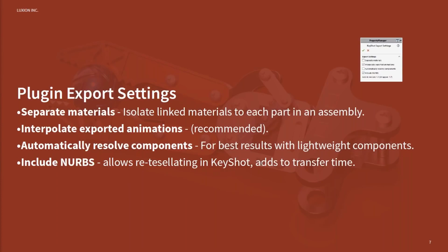And actually, for now, it is not remembered when you close and reopen SolidWorks. So just make sure to check those settings each time you're opening up a new session of SolidWorks, just to make sure that you have those enabled correctly. So if you do find that the transfer time is taking a long time, check to see if NURBS are included, and you may want to disable those.